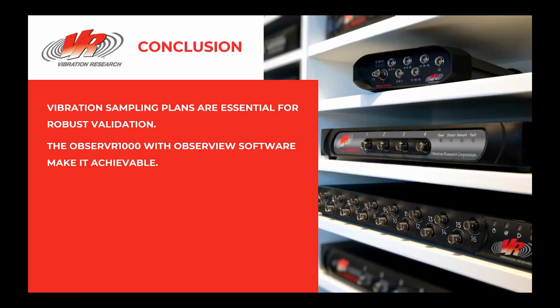So now you know about vibration sampling plans and why you need them. Identifying real failure modes for the correct reasons is essential for effective use of product development resources. For vibration testing, this means having the right data measured properly and correctly analyzed to correlate an accelerated test or virtual twin to a known amount of severe customer usage.